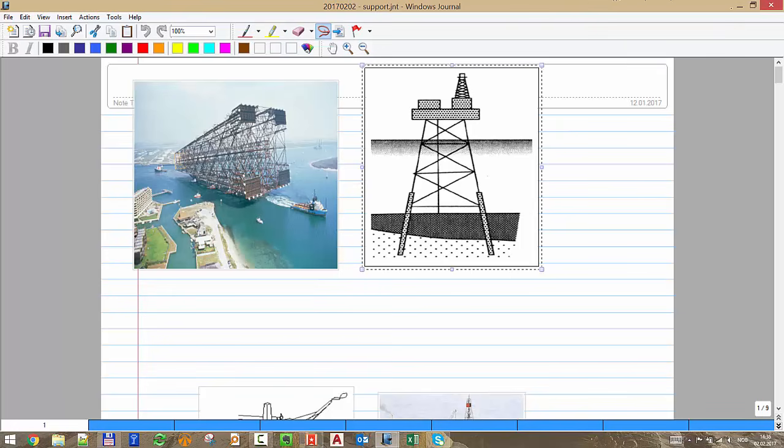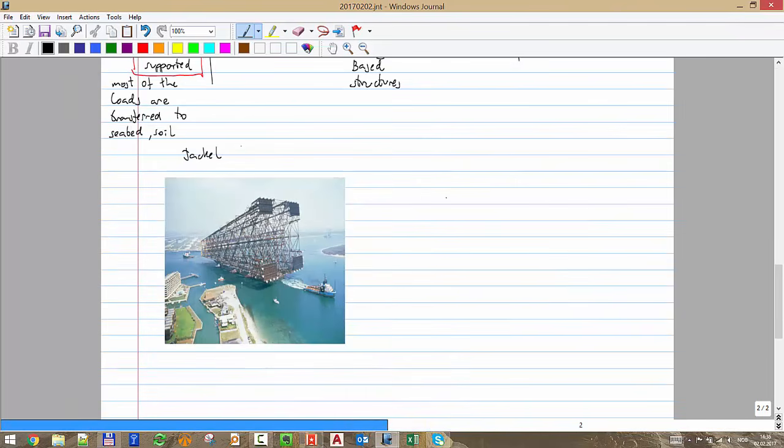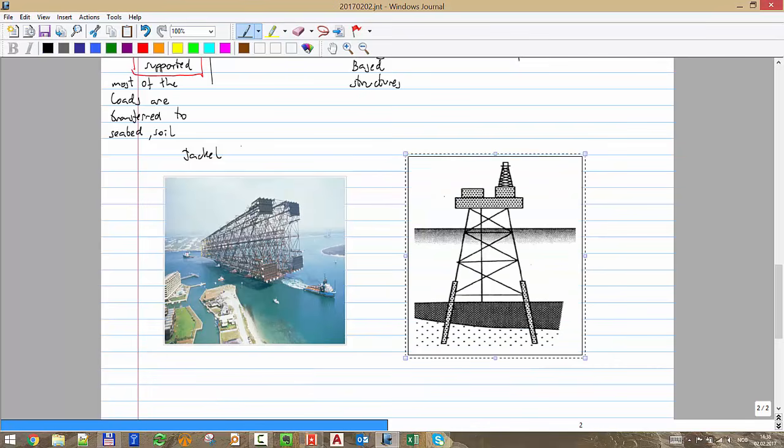Its own weight is not enough to keep it in place, even with the weight of the metal structure and of what comes on top. So you really have to drive piles that nail it into place. After you put it in location, you hammer anchors all the way into the soil, and that's how you achieve the transfer of forces from the structure to the surrounding soil.